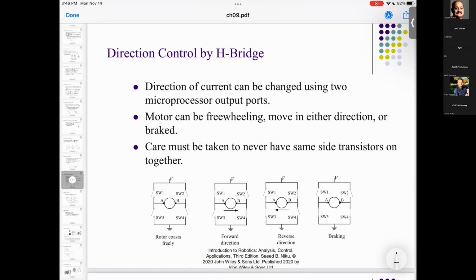Now, all that being said, I want you to look at the initial conditions that we wrote down. The first joint, the initial value is 0. The first joint initial velocity is 0 at time t equal to 0. The second joint initial displacement is 0. However, the initial velocity for the second joint is going to be 1, because look at it, d2 dot is equal to 1 multiplied by cosine 0.5t. So basically this will become 1. Then you have this 30 pi, which is the initial displacement of the third joint. And this is the initial velocity of the third joint.